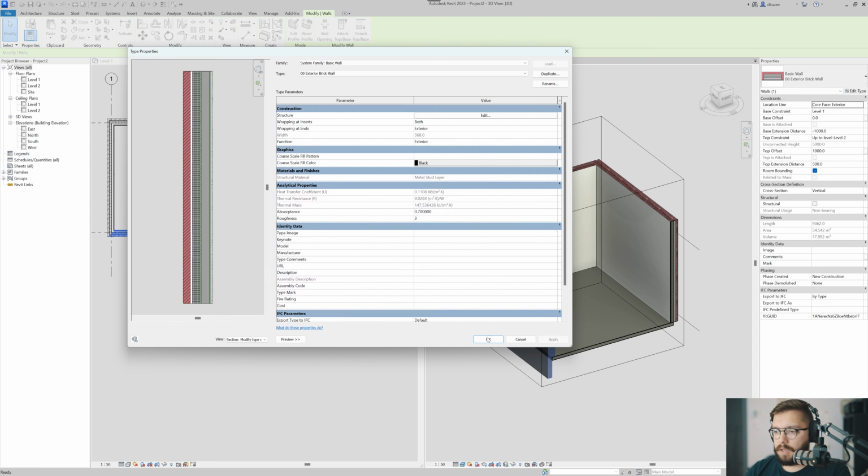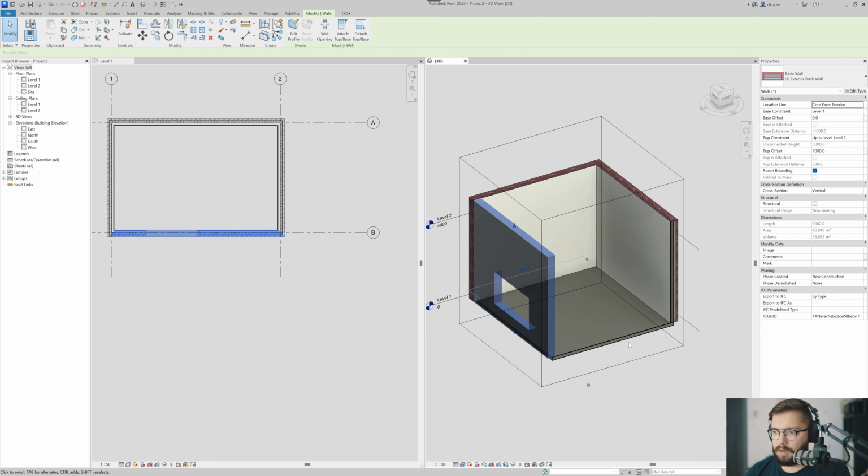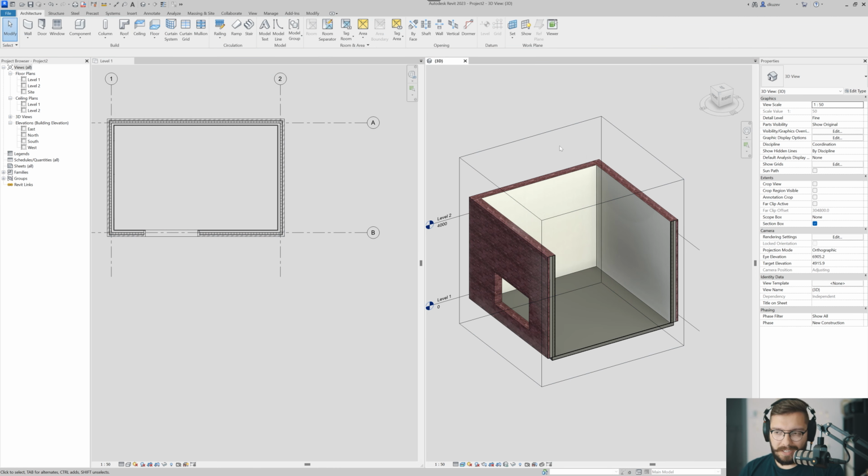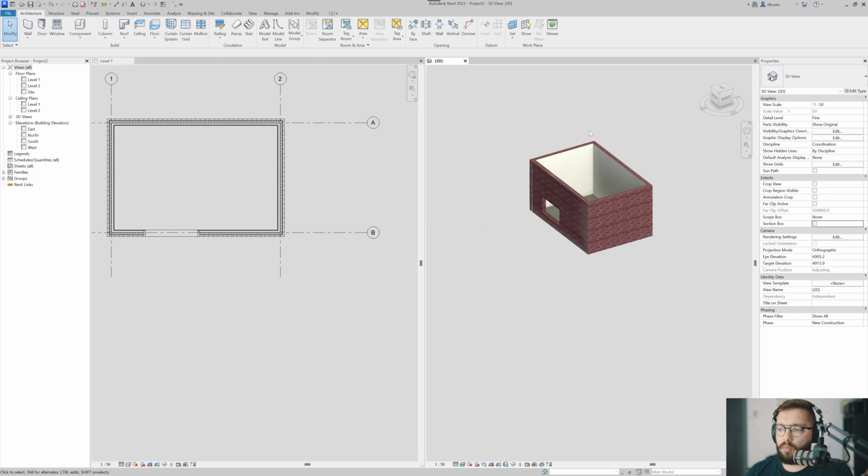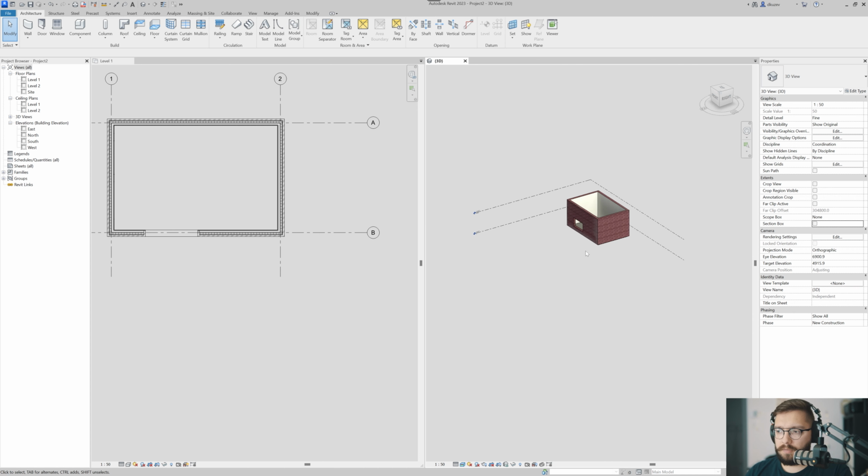Anyways, I hit okay, boom, now it behaves normally. Now, what a stacked wall is, well, it's in the name, but what Revit allows you to do is to actually have 2 walls on top of each other. And remember at some point I told you that Revit cannot allow to not have at least one of something? Stack walls is just another example.